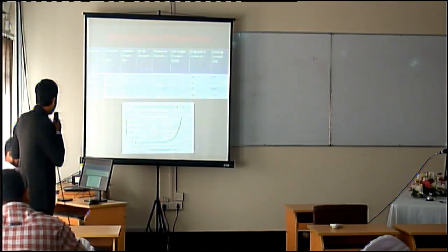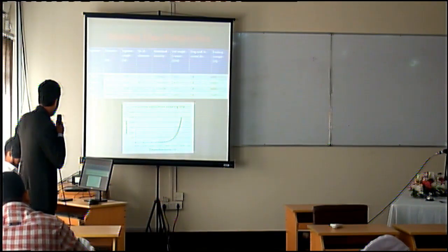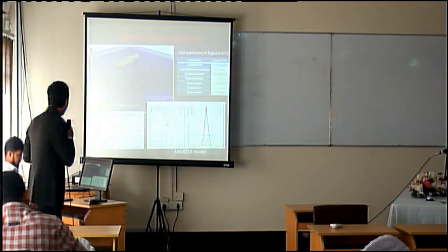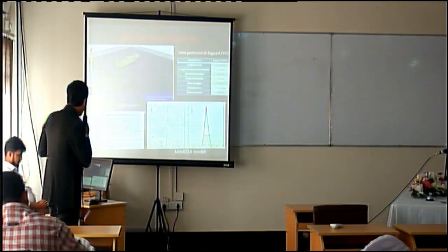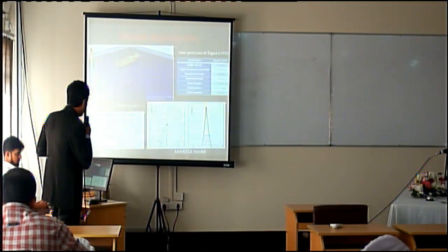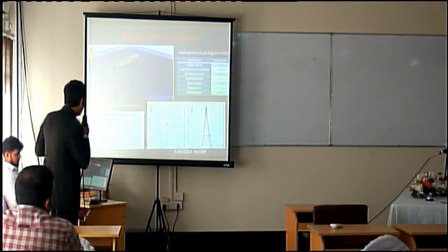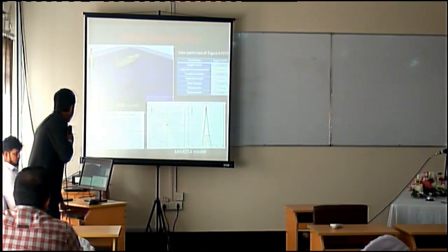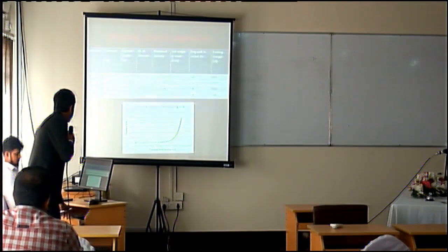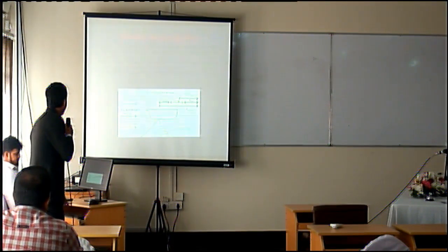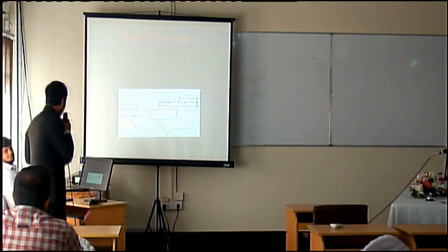Now the properties of my mooring lines, meaning how the mooring lines are connected at each point. Let's see, this is the anchor, and then the chain is connected here, and then the wire rope, and again chain. Okay, these are the forces we have applied: the wind, wave, and current forces.